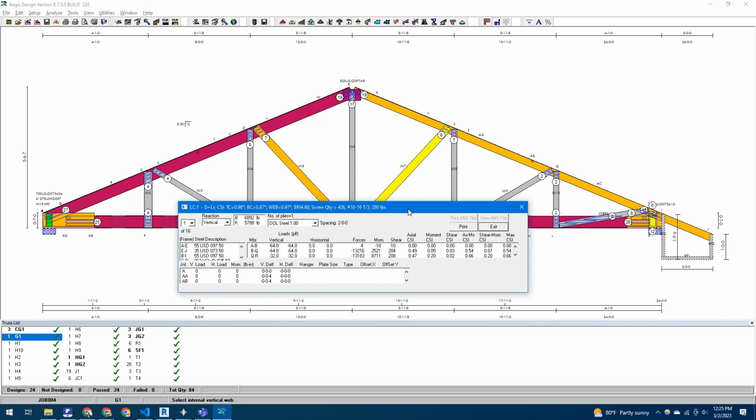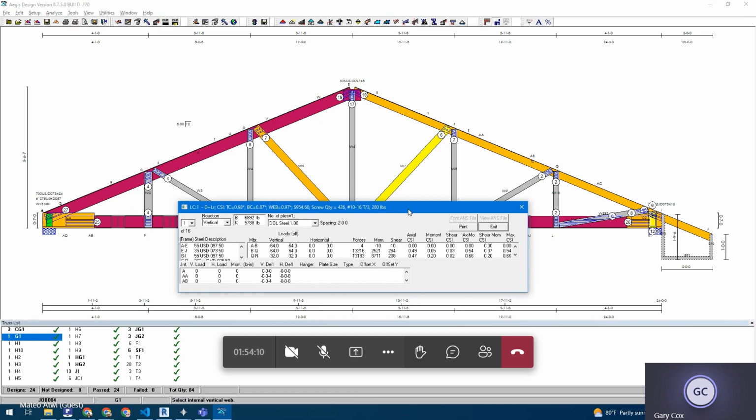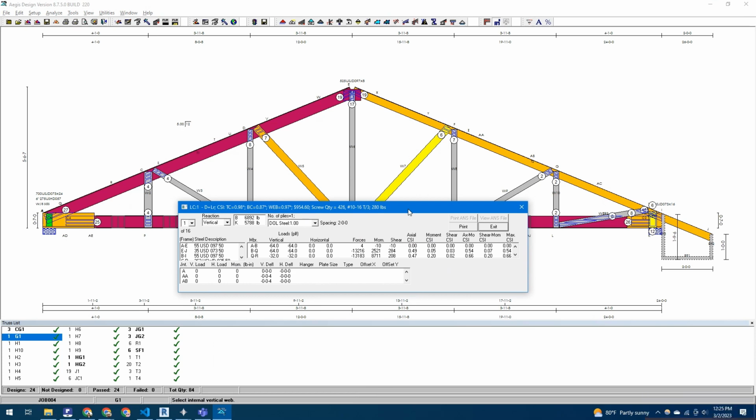You're going to have to decide, well, do I want to make it 2-ply and worry about the installer having to do more work? Or do I make it a 1-ply? It may cost them $20 more, but it's less work, and the installers may love you for only having one truss. Yeah. It's a balancing act, as you probably already know.